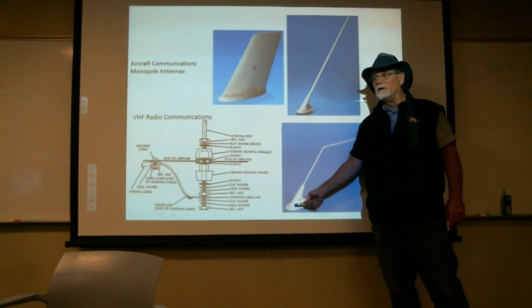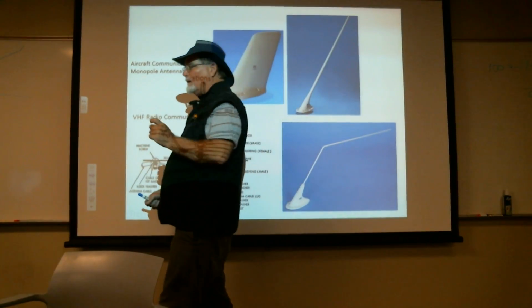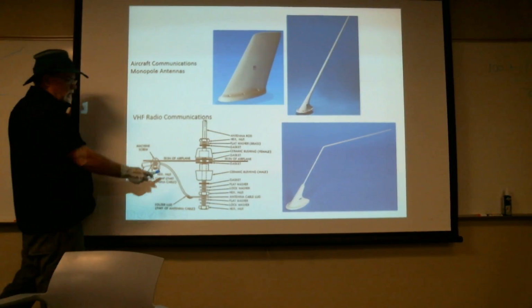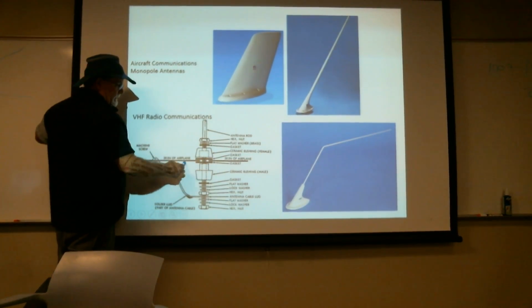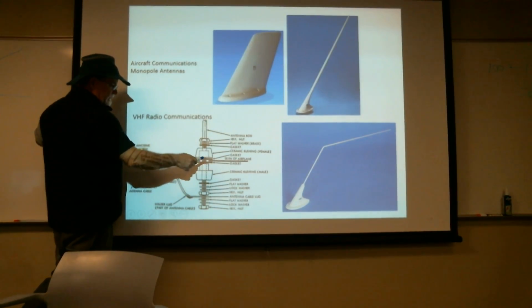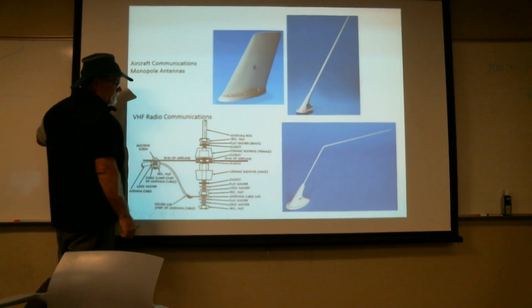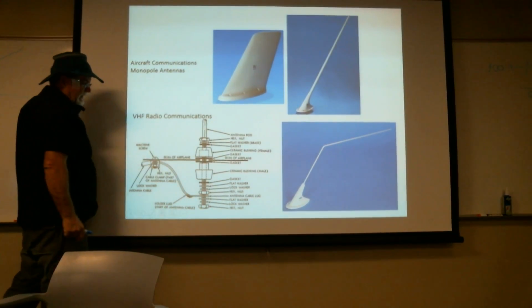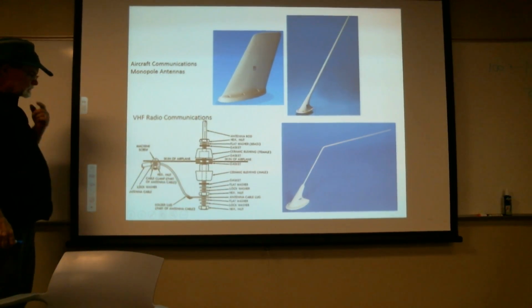So they've probably used an inductor in there to make the antenna seem a little bit longer than it really is. This here is the one I was trying to draw, where you've got some insulator, maybe a couple of gaskets, and maybe even a stiffener in there. The two insulators come together. The antenna rod comes out here with a couple of clamping nuts to hold it in place.